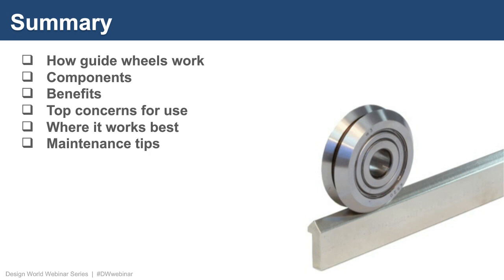We talked about different terminology and jargon with the different types of linear guides: guide wheels, square rails, round rails, sliding element bearings. We talked about a couple different drive mechanisms: belts, chains, ball screws, lead screws, and rack and pinions. We briefly touched on actuators, linear actuators, rotary actuators, and what those mean for a motion system.